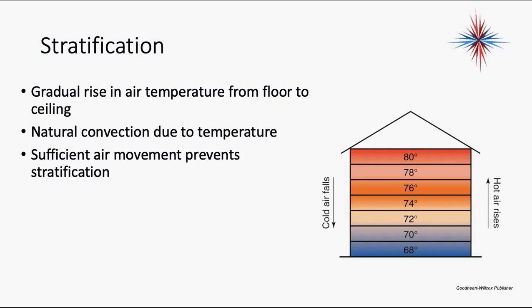High-ceilinged rooms used to be part of the building trends before we had a standard of air conditioning. You built your rooms with extremely high ceilings, so when you were standing at floor level, the air was colder. Now that our ceilings are lower, that doesn't work as well, so we have to worry about stratification.